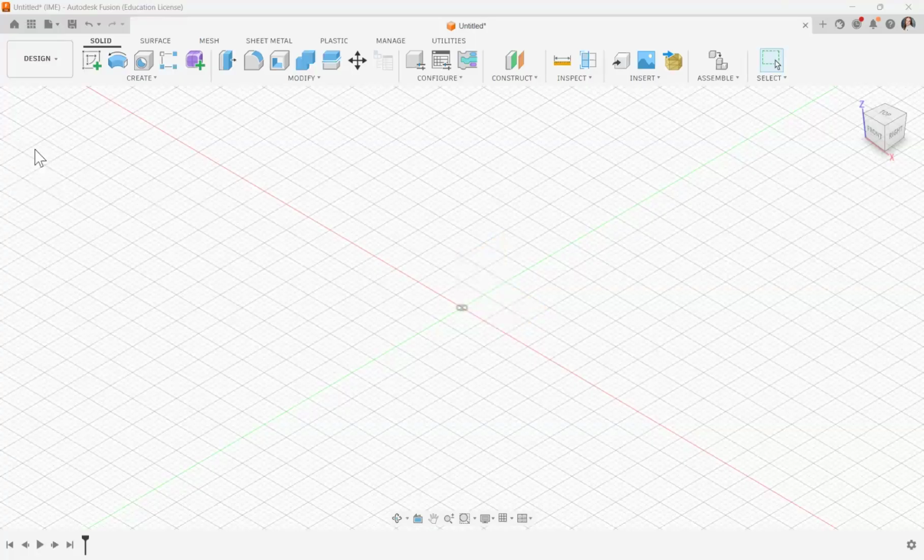Okay. So I want you to look at document settings. We're going to be making our drawing or our sketch in inches because that's what our deliverables say in Blackboard for the coaster project. So if this is not what you see, you might see millimeters. Click on this button here, which is change active units. And you will see that you can select this drop down menu and change it to inches. Okay. And I have mine set to default. So if you want to do that, you can click it and hit OK. Or if not, just leave it.